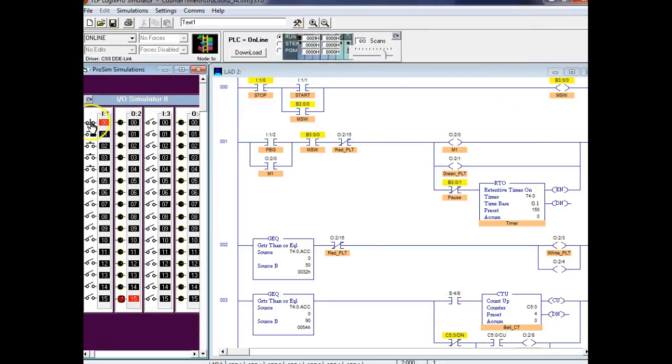What's supposed to happen here is we're supposed to have a master start stop. The book says a master switch. We enable the thing with the master switch. Then we have another push button, the green push button, and unfortunately we can't change the push button colors. Then instantly a green light's supposed to come on and the motor's supposed to run.